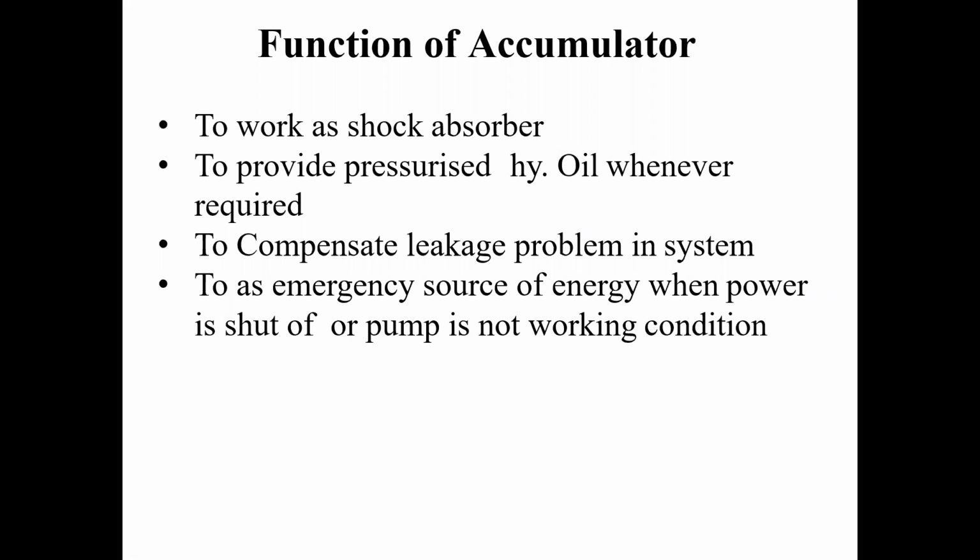So here we go to see the functions of the accumulator. First, to work as a shock absorber. What is the meaning of shock absorber? Shock absorber means when there is vibration or some unbalanced force produced inside the system because of the pump, this high pressure wave is absorbed by the accumulator, which works as a safety device for the hydraulic system.